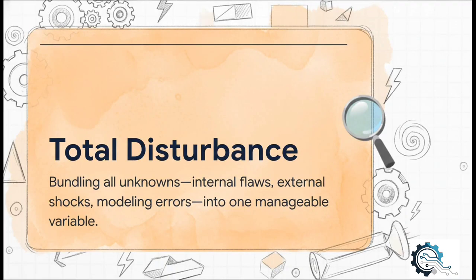Okay, the absolute core genius of ADRC comes down to this one idea, the total disturbance. Think about it. Instead of trying to model every little thing, like the friction in a valve, or the changing quality of the coal, or how different parts of the system are interfering with each other, ADRC just says, you know what, let's just lump all of that messy, unknown stuff together and call it one thing, the total disturbance.